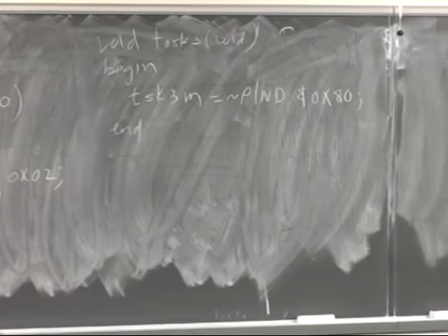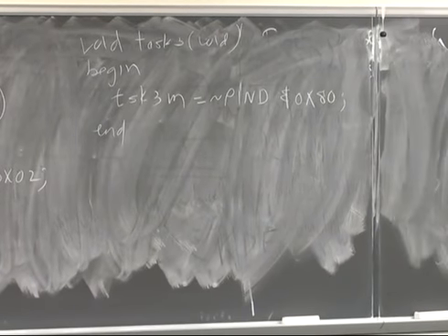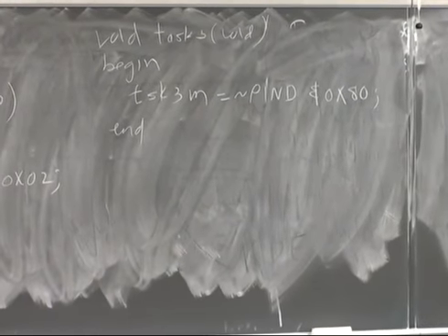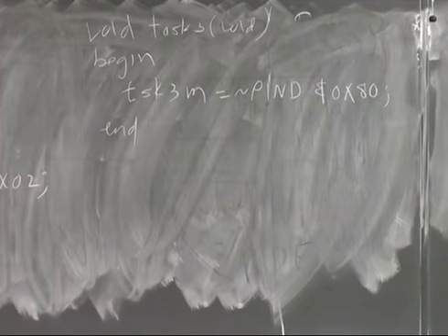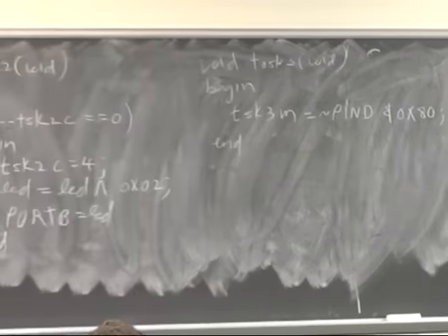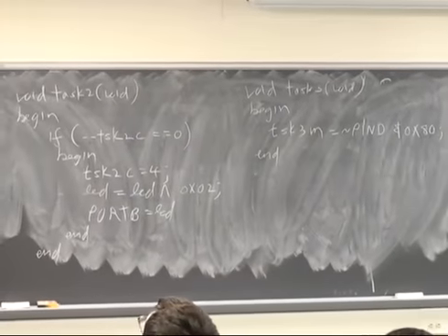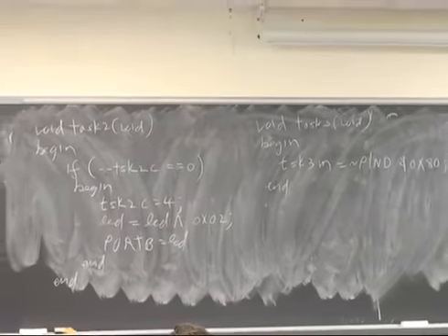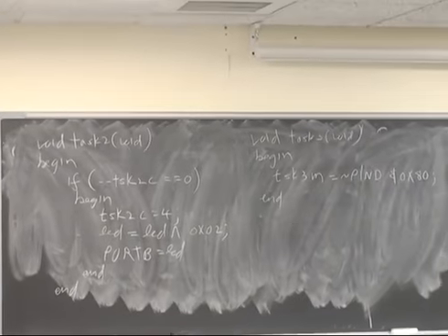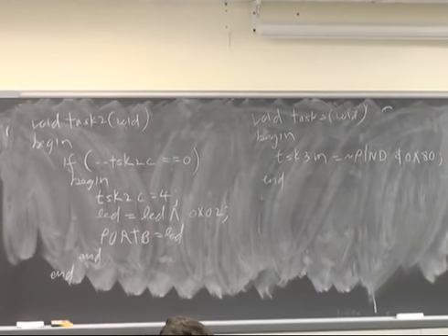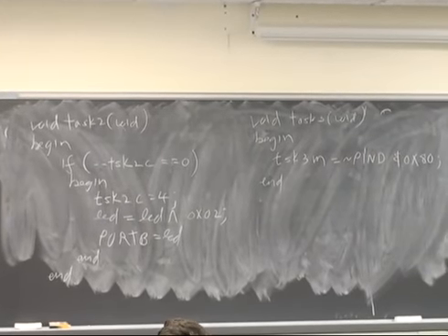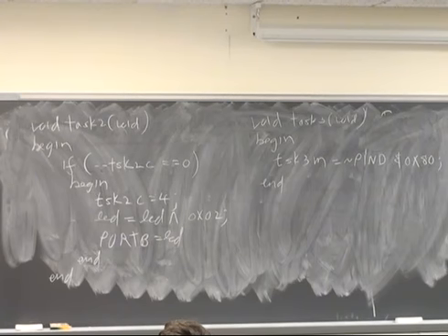Why isn't time 2 just 500? Can't be 500 because I use byte variables. And the maximum size for a byte variable is 255. So if I bothered to recode this from the assembly language using integers rather than bytes, I could have done it directly.